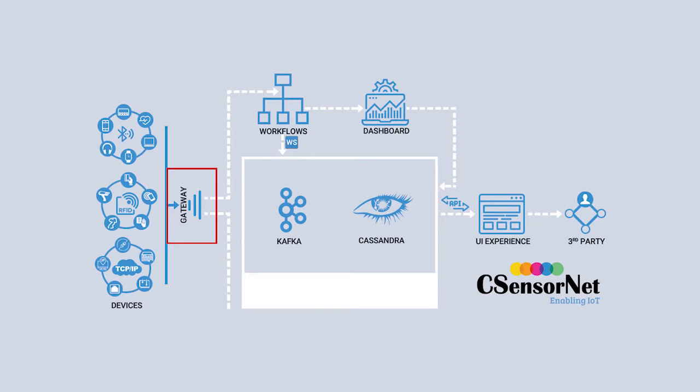The next component, Node-RED, is perhaps the heart of CsensorNet. Node-RED is IBM's open source IoT product. It resides on the gateway and comes as part of the Raspbian OS. Node-RED enables CsensorNet to enrich or transmit data as is through easy-to-create workflows. Its primary purpose is to stitch together web services and hardware by replacing low-level coding tasks. It also has a very lightweight runtime environment. Event-driven and non-blocking models, local or cloud deployments, and simple mechanisms to import or export workflows as JSON make it ideal for IoT.